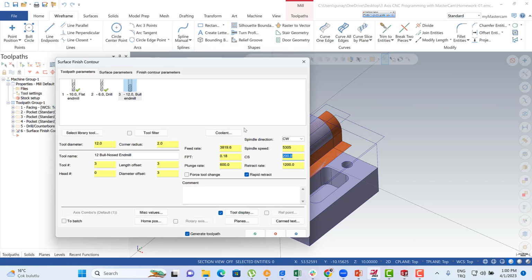But if you use this one as a cutting speed, your tool wear is going to be better than the 200. So this is the best way to see less tool wear in your process. But of course that also reduces our feed rate.